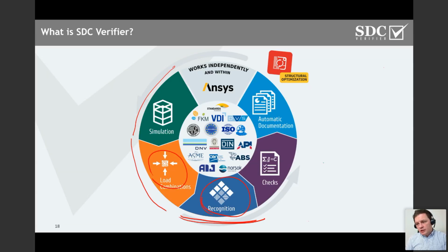Because if you have any kind of basic automation, you check it on one loading condition for one single structural member. SDC Verifier analyzes your complete Ansys model under a fairly unlimited amount of loads and combinations, especially if we speak about offshore structures and sea motions and winds and all of the possible combinations for spectral fatigue.